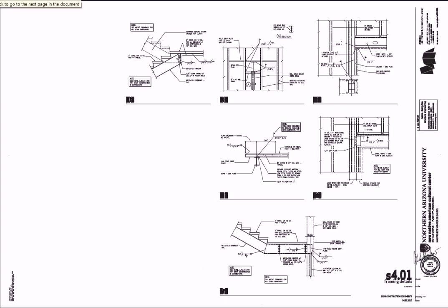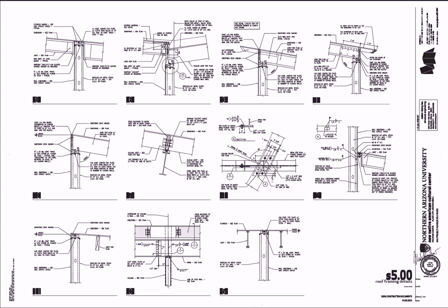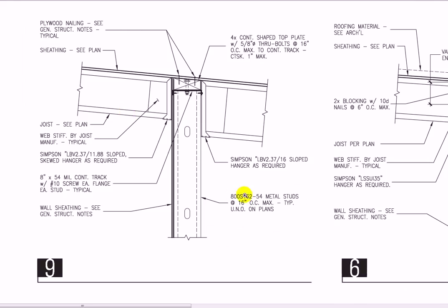A couple more framing details. This looks like I got some ways that the stairs are connecting together. Now we get up to the roof framing details. So I see a lot of slants here, which tells me there's going to be some complexity to this job. Just zoom into one here. Again, we have metal studs, bearing walls, and then we have joists. So I'm not sure quite what these joists are. I see plywood. I'm guessing that these are probably wood joists, and we can see a slope to it. So now I'm seeing this complexity of the building, that we have a sloped roof going on.